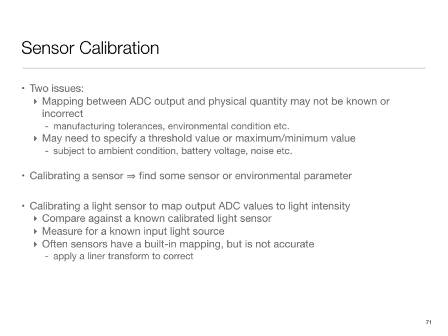Then the other thing which happens at a lower level is sensor calibration. What this refers to is how you relate the number coming out of the A to D converter to the physical quantity of interest to you. For example, let's say you are measuring the concentration of a molecule in water. Your A to D converter is giving some number because you pass some current through the fluid and you are measuring the voltage, and you have some reading. What concentration does it correspond to?